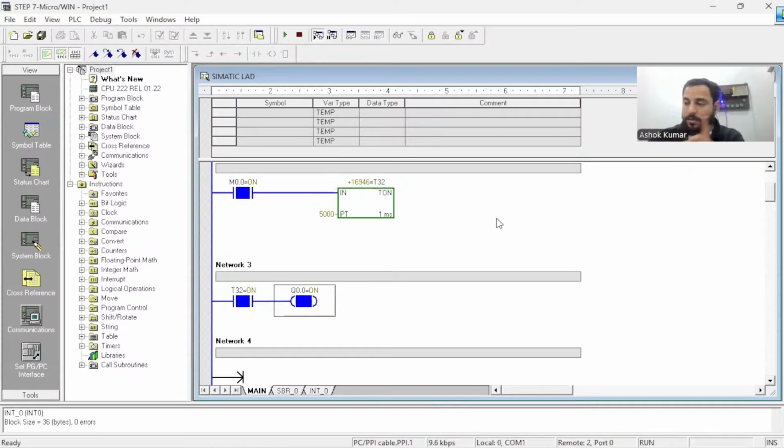When we did Allen Bradley, once the accumulator achieved the preset value, it was stopping. But here it does not stop. It will go up to the max value, which is about to come, 32767. Stop now. But how did we come to know that the task is completed? Done bit. Just after 5 seconds, the done bit was high, right?